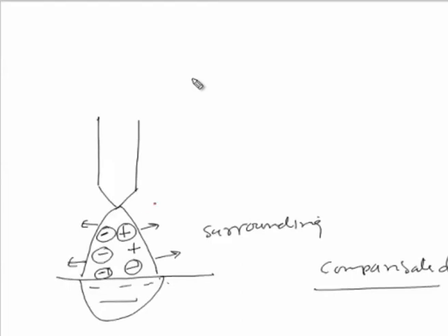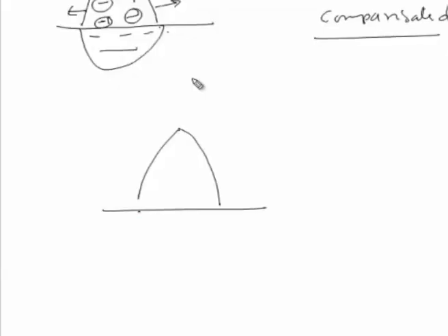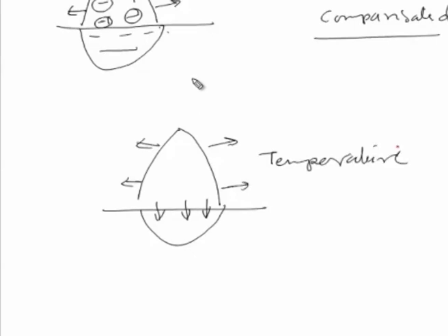otherwise these will decrease the number of charged particles in the arc gap, which will make the flow of current difficult. Another important aspect is that heat will be lost from the arc zone to the base material and to the surroundings. This heat loss will decrease the temperature. So, the reduction in temperature will decrease the thermal emission and other aspects, which will further decrease the presence of